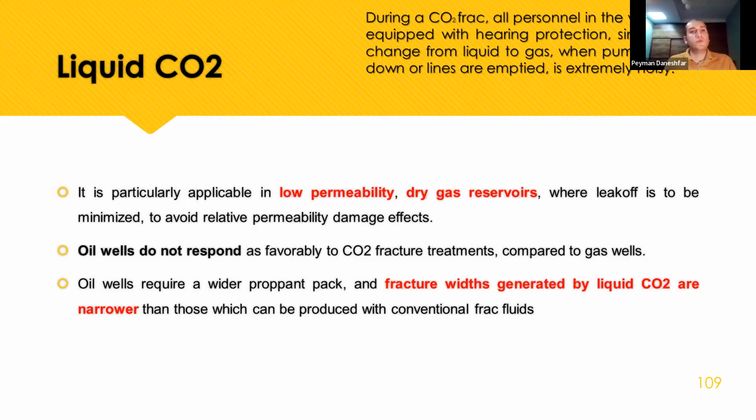Oil wells do not respond as favorably to CO2 fracture treatment compared to gas wells. So oil wells, forget about them in liquid CO2 fracturing. Because oil wells require a wider proppant pack, and the fracture widths generated by liquid CO2 are narrower than those which can be produced with conventional frac fluids.